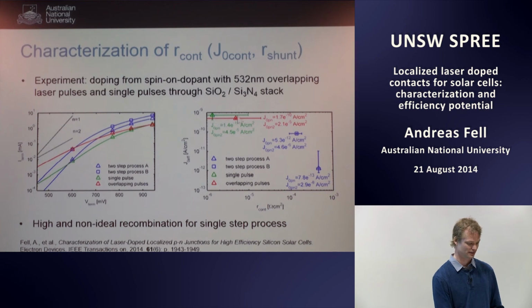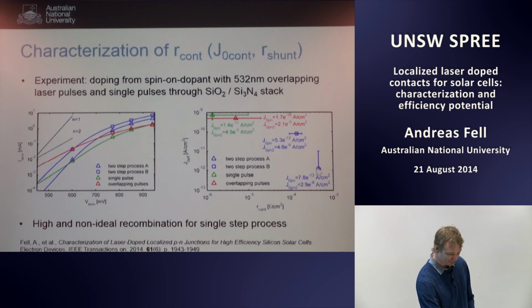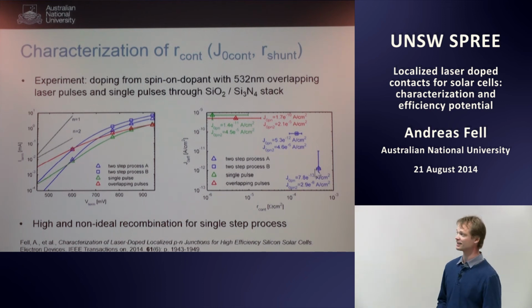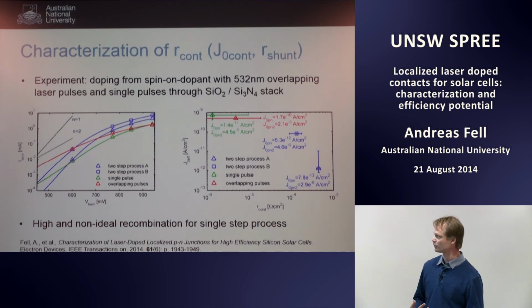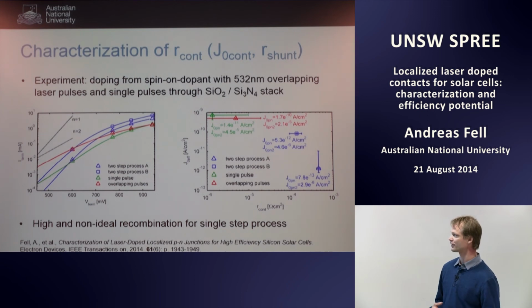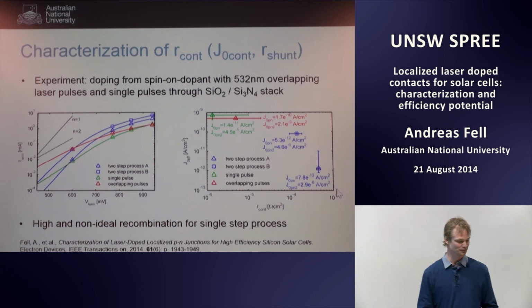So that's, what was it he said, maybe 1 million femtoamps. But there's at least one process which worked nicely. That's a 2-step process, which gives you actually below 1,000 femtoamps per square centimeter. And contact resistance is still good enough because it's below 1e-3.